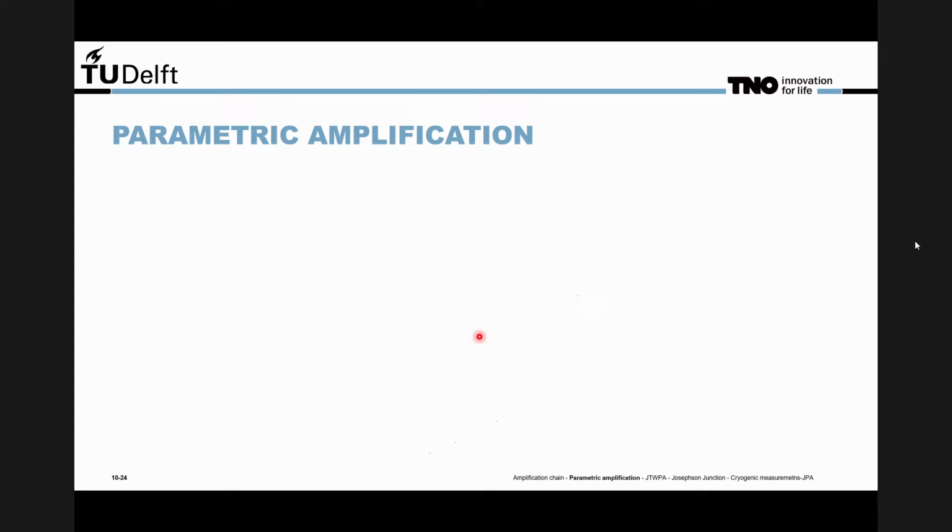So parametric amplification. This is another type of amplification which usually requires an external power source to modulate one parameter in the system. This power source is usually referred to as the pump. The added noise of this amplifier can be very minimal compared to other amplifiers, as the energy of the pump goes to a parameter inside of the system instead of being directly added to the signal.